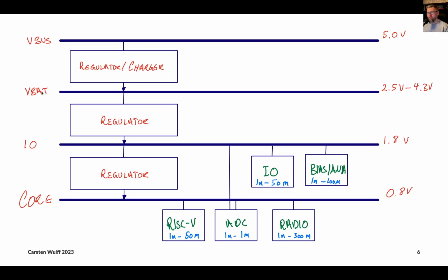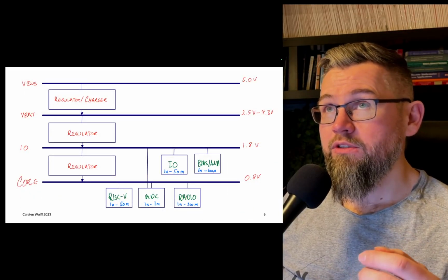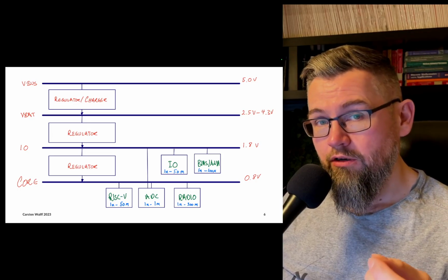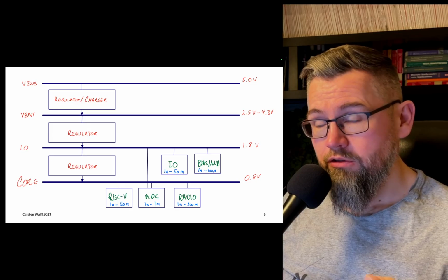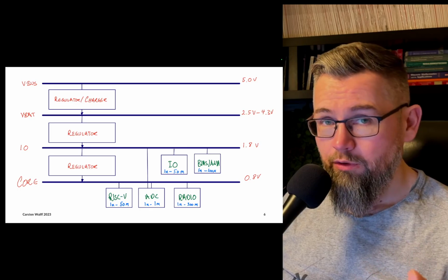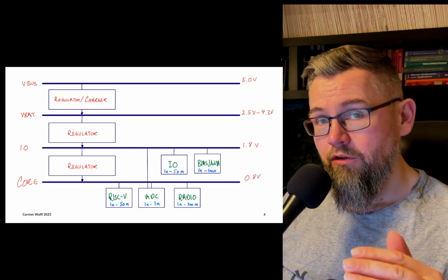Now, if you're going to charge a lithium-ion battery, you actually have to get a bit careful, because when you're charging a lithium-ion battery, you have to transition from initially very low current, and then to a constant current charge. And as the voltage increases towards 4.2 or 4.3 volts, you have to go over into a voltage control type of charging.